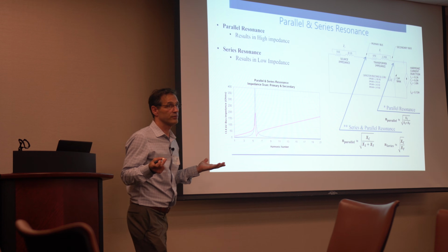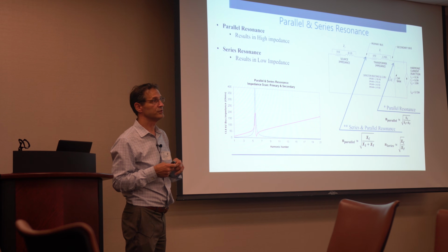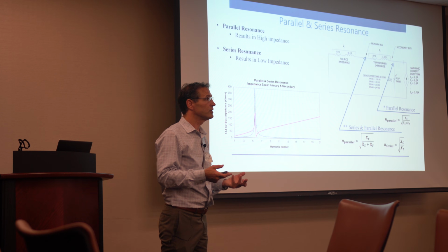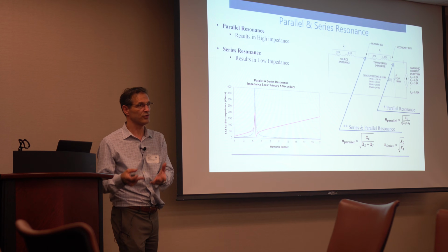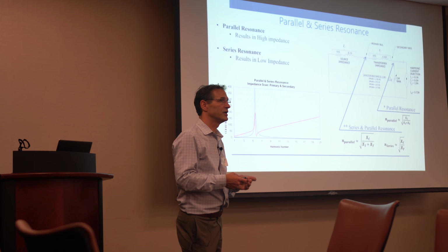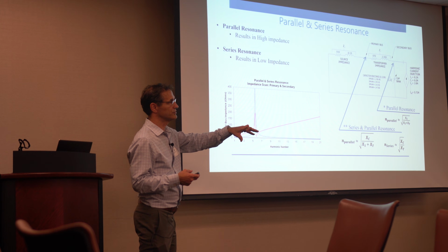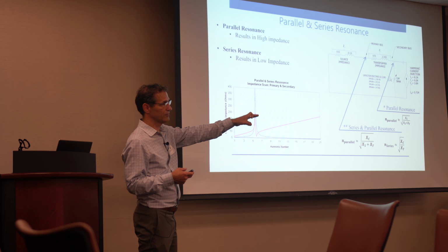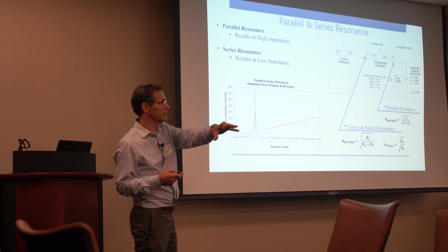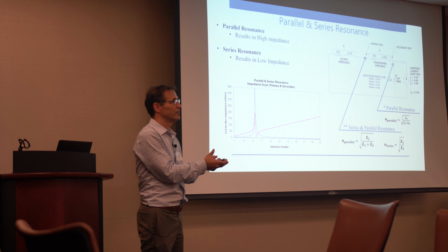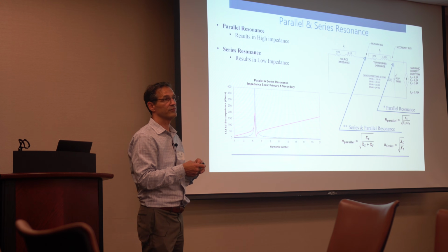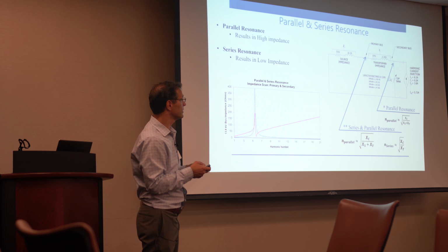For us, we would recommend medium voltage. It's a good place for it. At low voltage, you can't get the megavars you need. It takes too much. At medium voltage level, it comes in at a lower cost, with fewer stages, less complexity, and less current. At transmission levels, you have to switch this, and that comes very expensive too. Plus, you're closely coupled with the transmission network, which is owned by the utility, and they have their own things they're doing. You have other customers local to you that might be adding capacitor banks, or you might be trying to put a filter in, so it makes things complicated. So a medium voltage network is a good place to add reactive compensation, whether it's capacitor banks or harmonic filter banks.